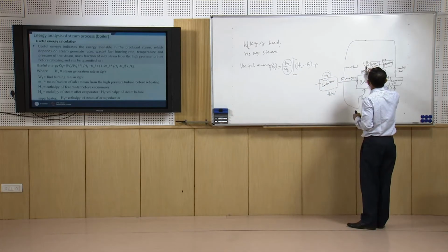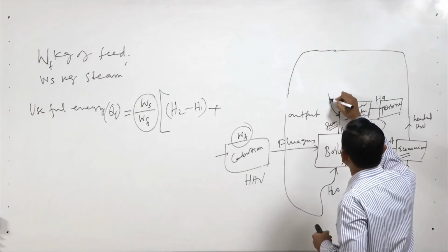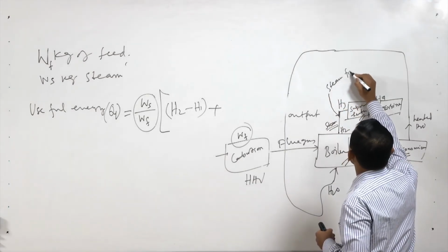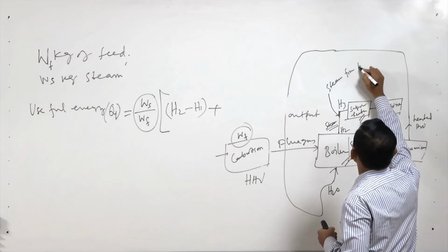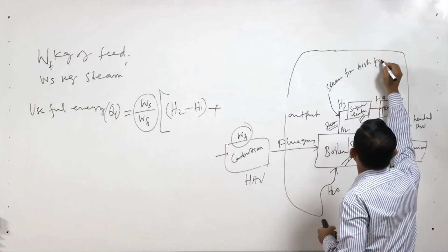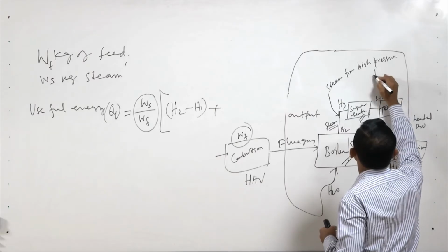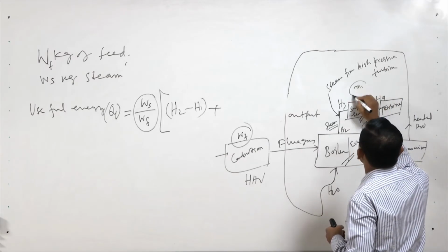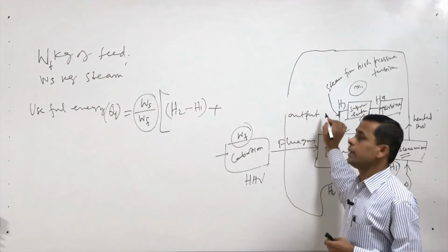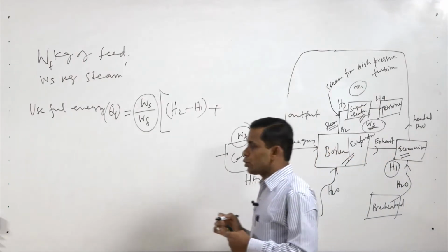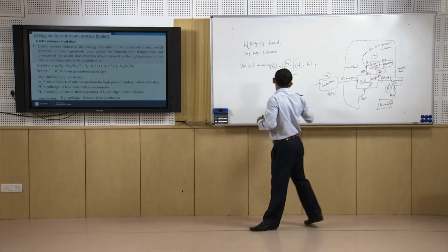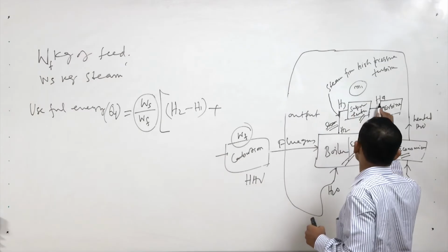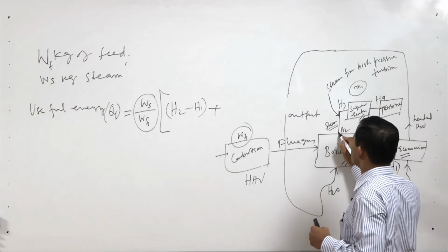The steam from the high pressure turbine can be used here. So, we are assuming that M1 mass fraction of steam is added in this place. So, we do not need to raise the heating value of all the steam from H3 to H4.